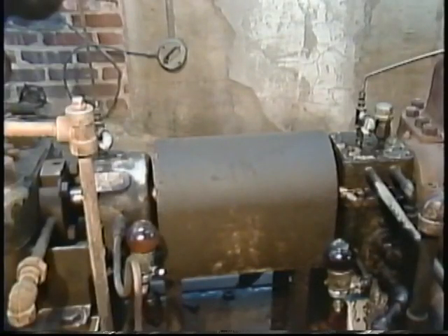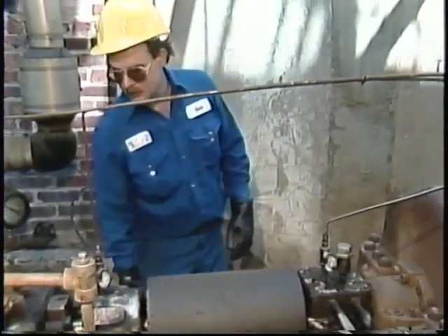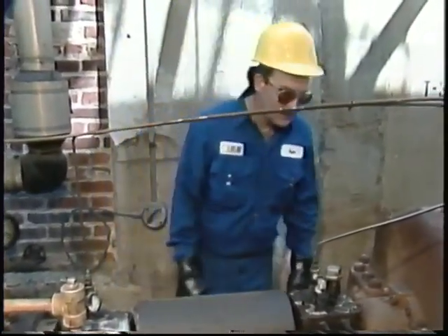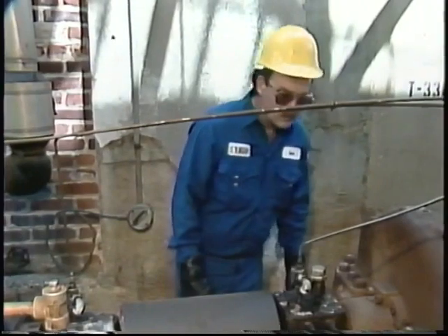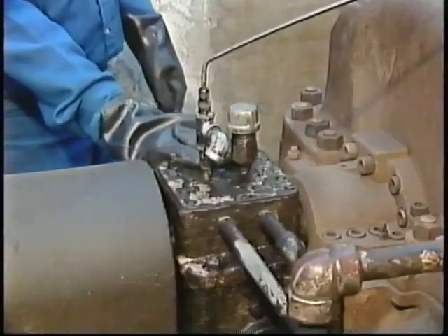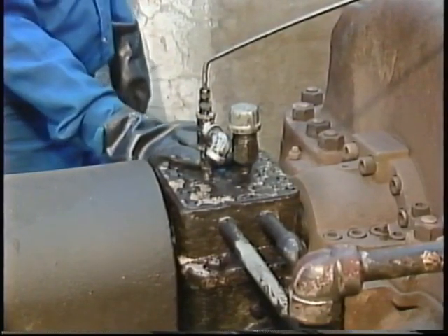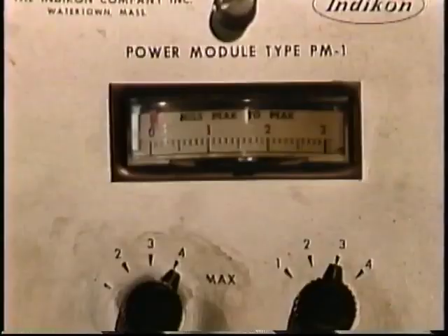This condition can be caused by problems in the turbine, the coupling, or the driven equipment. Sometimes you can hear the vibration and tell if it's coming from the turbine or the driven equipment. But some vibrations may not be able to be detected by listening for them. Generally, your sense of touch is a better means of identifying and locating the source of the vibration.